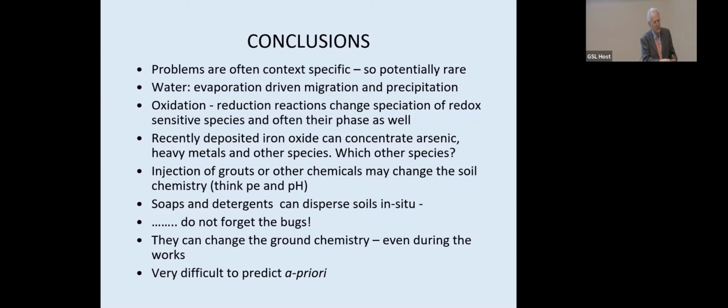Hydrogen sulfide would then strip the passive oxide film off the stainless steel, and then it would react quicker than mild steel with the acid elsewhere. So you can get niche environments. Bacteria don't work globally, so to speak. They can also work in niche environments. So niche environment, bit of carbon, sulfate, not too acid, because the sulfate reducers don't really want to be too acid.